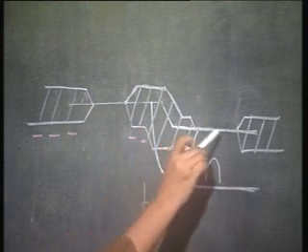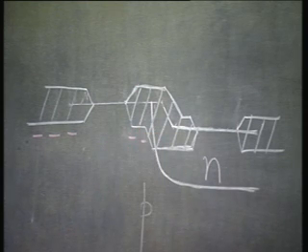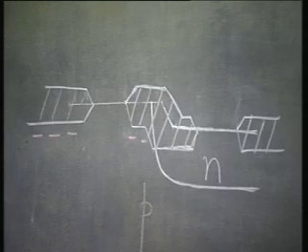Then you carry out the drive in an oxidizing ambient, so that the Nwell is driven deeper, and at the same time you have a thick oxide forming on the Nwell. After this, you do the stripping of nitride as well as oxide. Because there was a thick oxide formed on top of the well, you have a step in the semiconductor surface which helps you to identify the Nwell regions.